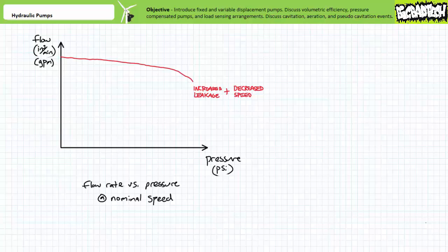The graph doesn't explicitly tell you that the prime mover slows down at increased pressure requirements, but it does quite nicely show you that flow rate is a function of pressure. Note the graph restricts pressure to a certain range, outside of which increasing nonlinearities exist. Manufacturers therefore restrict their flow rate analysis to a certain ideal pressure range above which the pump is not intended to be operated due to possible damage to seals.